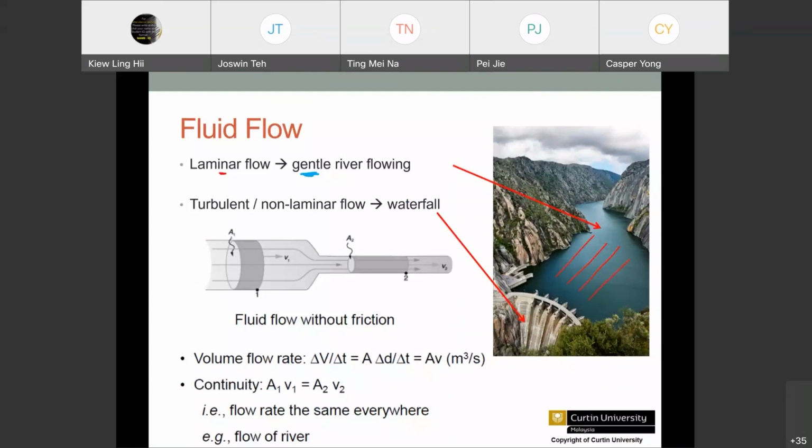So if you have ever visited our lab before, there is a laminar flow cabinet whereby this cabinet is used in order to conduct some microbiology experiments, because we know that the germs, they are very, very tiny, very, very small, right? Imagine as spores. It is too small, when there is a flow, it can bring the spore to move together with it. So we need the laminar flow so that there won't be any cross-contamination.